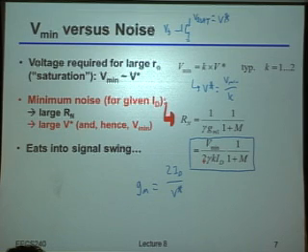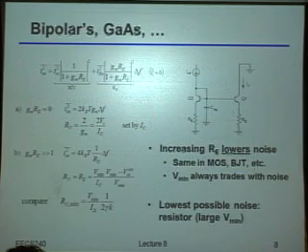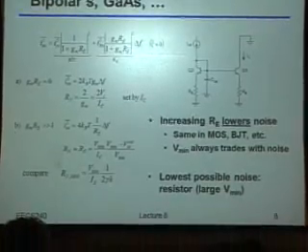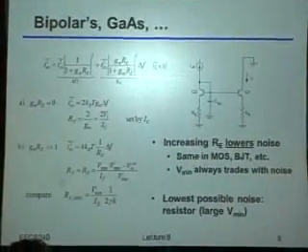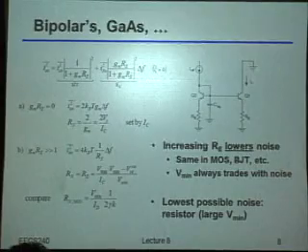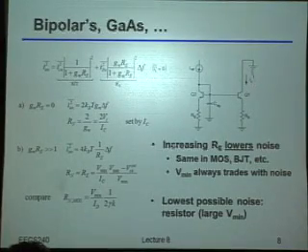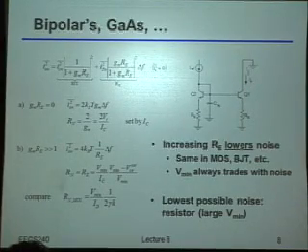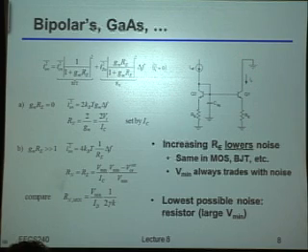So, just to be sure that this is 100% clear, I just want to show one more example. Okay? You'll notice here that I now switched from CMOS to bipolars, not because we're really going to be doing anything with bipolars here in the class, but just to make sure that this concept is pretty clear. So if you'll notice in the circuit on the right, rather than just doing an exact bipolar version of the CMOS current mirror, I added in these degeneration resistors.